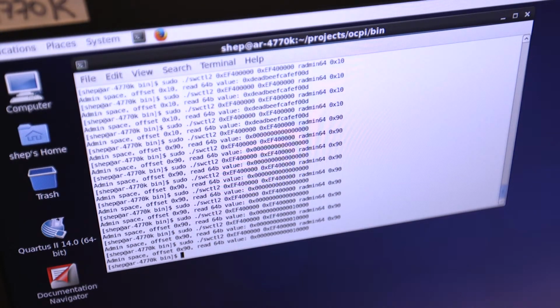And if we now switch off the generator again, pressing the off button, and go to read 90, we see that goes to 0. So the bit 16 in the 64-bit location hex 90 from the base of BAR 0 indicates the lock status to the 10 megahertz external reference.